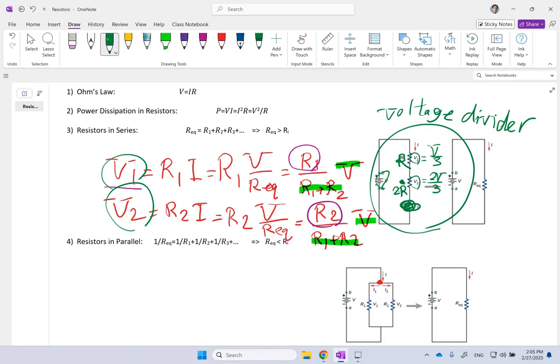And when you have a rheostat, what you have in a rheostat is these two resistors side by side, but this junction point is determined by the location of the slider, because the whole thing is like resistor, resistor, resistor. So when you put it here, one of your resistors will be this, the other one will be this.